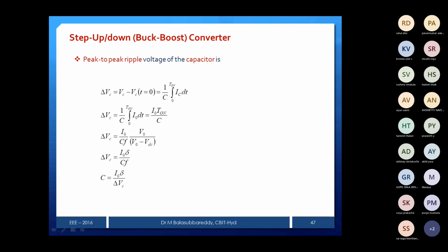The only thing is, when you are doing the problems, you require these relations. Just practice once. Any buck or boost or any one, it is only a replacement. The voltage across the inductor, VDC, may be replaced by Vin minus Vout like that. That changes only, all other things are the same. So this is the end of the first half of the unit that we call choppers.